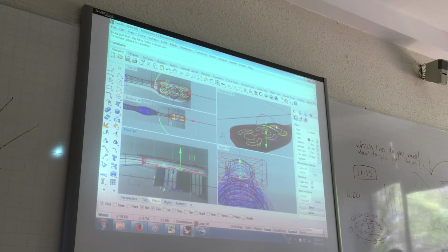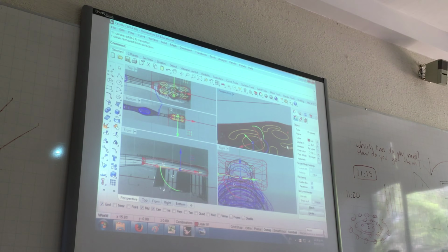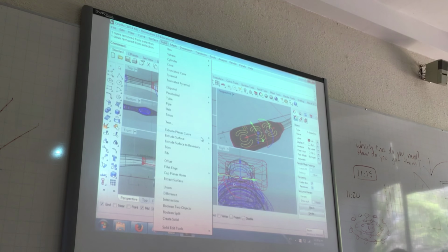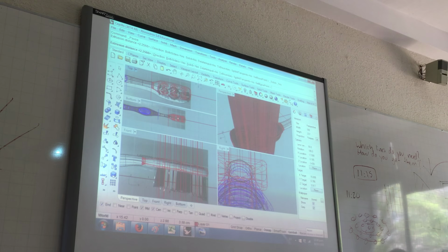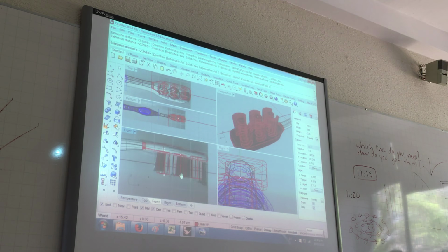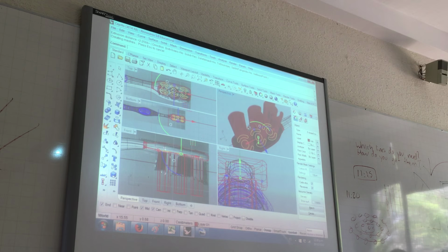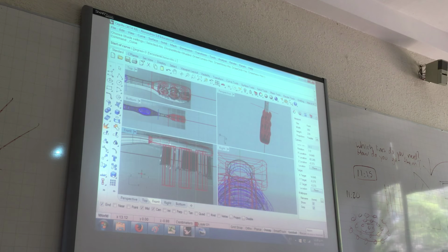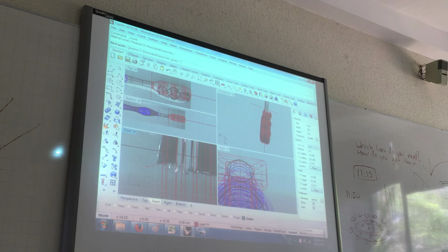So I'm going to select them all, minus the ones in the center. And as you said, I'm going to extrude them. Solid, extrude, straight, both sides, no. And I'm going to make them this big. I forgot to, no, yes sir. So now that I have them like this, I'm going to draw a line that passes through this shape. Let's see if you understand what I'm doing.